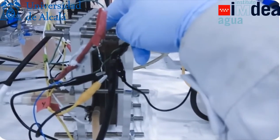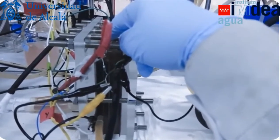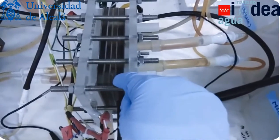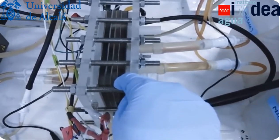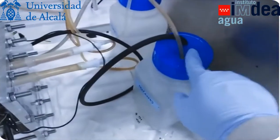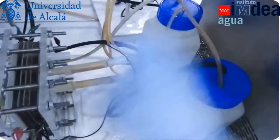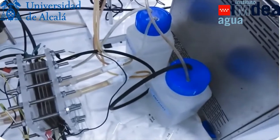In chamber A, we already have anions like Cl- and phosphate, so they will react with H+ and will produce corresponding acids, for example HCl or H3PO4. And in chamber B, we already have some cations in the form of Na+ or NH4+. They will react with OH- ions and will produce NaOH or NH4OH. So these acids and bases are collected in these acid and base collection containers. We recirculate the collected acids and bases through these chambers continuously, so that we can get more acids and bases.